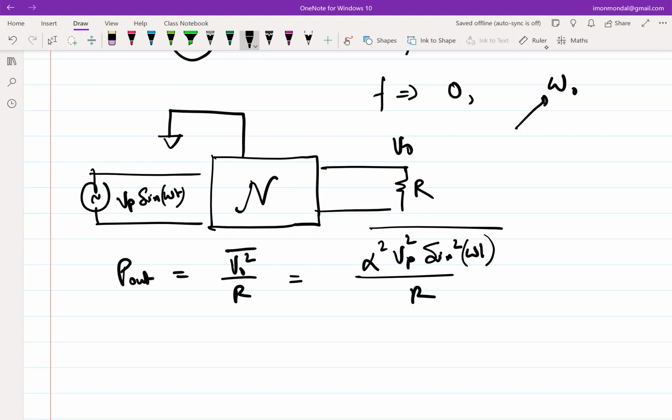Why am I able to completely chop off VDD? Because it is LTI. Superposition is not valid in a nonlinear system; superposition is valid in LTI. That is why I can chop off VDD, which means I can treat each source as if no other source exists. I can do my analysis by de-energizing other sources. This is the sole reason why, if a source is operating at a certain frequency, you cannot transfer the power from that frequency to another frequency, because all the operations are linear.